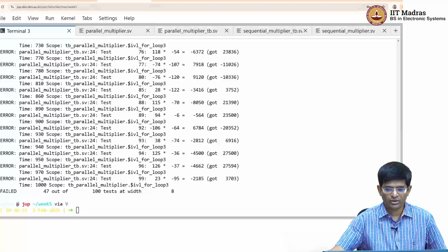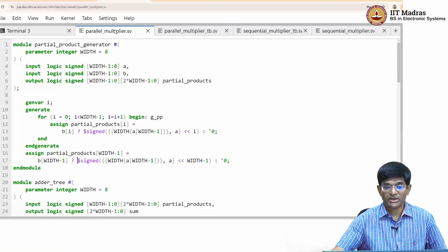And sure enough, I find that wherever I have a negative multiplier out here, in all of those cases, my final result ended up coming out wrong. So it's always good to make sure that your test bench actually does catch scenarios with error. In fact, one of the approaches for design, which is called in some sense test driven design, is to say first write out your tests, make sure that all the tests fail, and then start adding code which passes one or a few tests at a time, so that you know exactly which code has solved which problem. Ideally, it shouldn't be that one change in the code that you make solves all your problems at once.